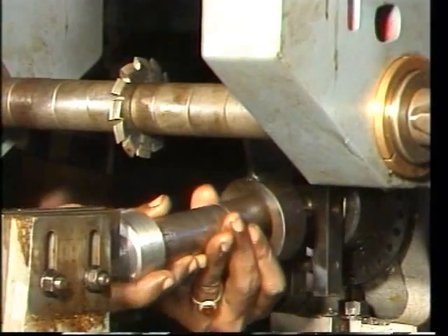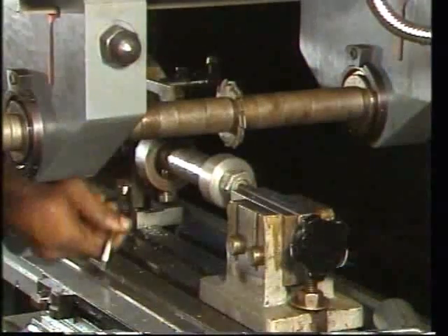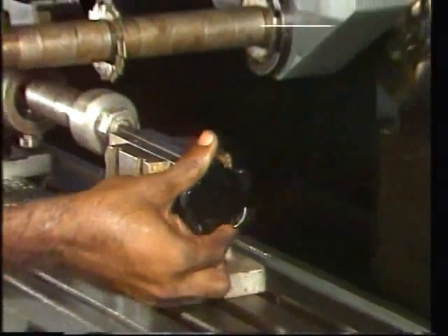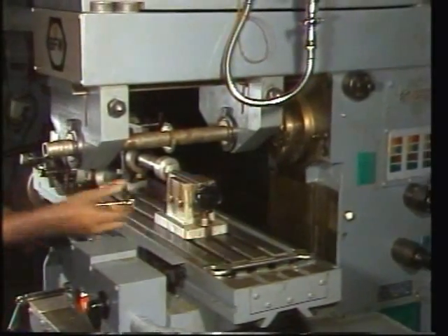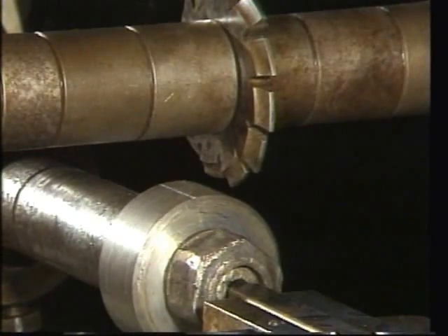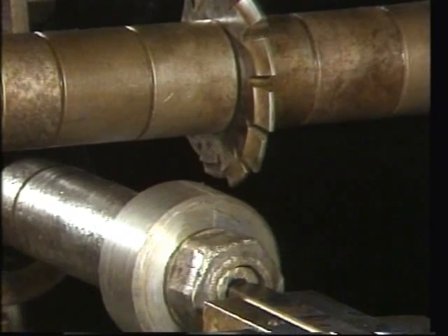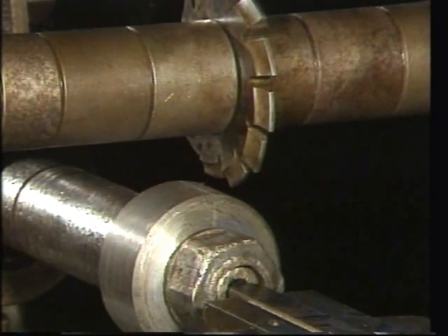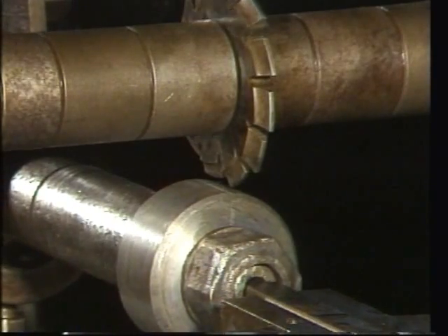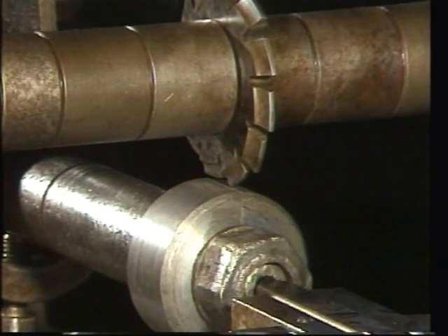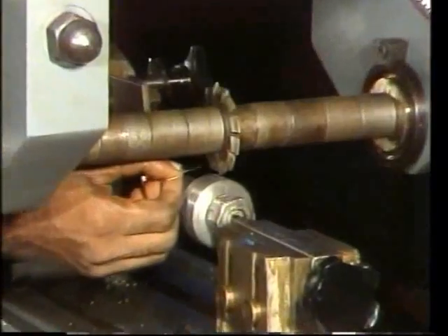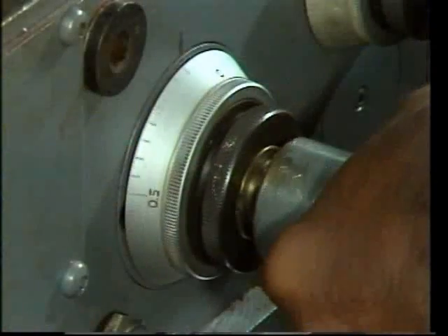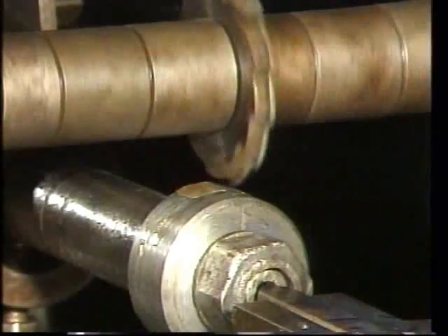In order to fit squarely on the fixture, the blank dia, the bore, and the working faces are machined true to each other. The job is moved so that the cutter is centered to the marked line, and thus centering of cutter is obtained. First zero setting is made using a thin paper to judge the exact contact point of the cutter on the job.